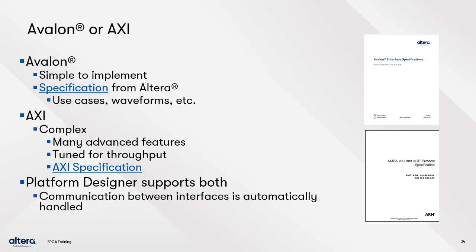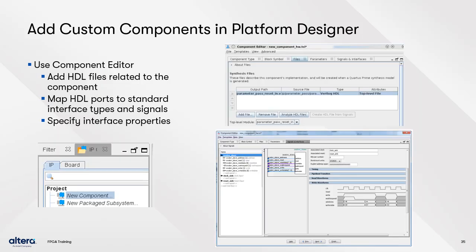But if you would like to implement complex interfaces that include security, then AXI is the way to go. Before custom components can be instantiated in Platform Designer, you'll need to create them. The easiest way to do this is using the component editor.